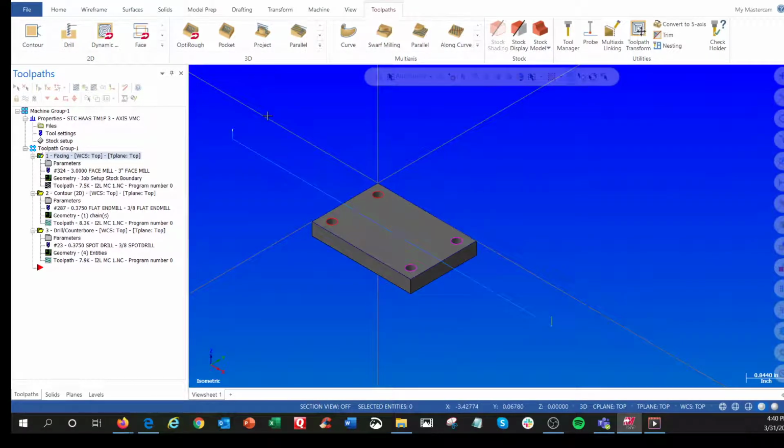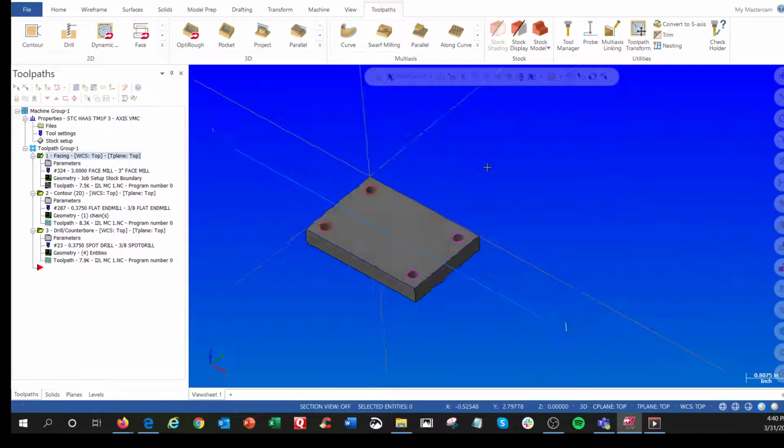So you have to do a tool change, reposition, call up your work coordinate, get the spindle spinning, bring it down rapidly, stop somewhere above where you're going to start your cutting moves, and then feed down, which would be a G1 move at a controlled feed rate. Then we're going to go this way, which is just a simple G1 move.